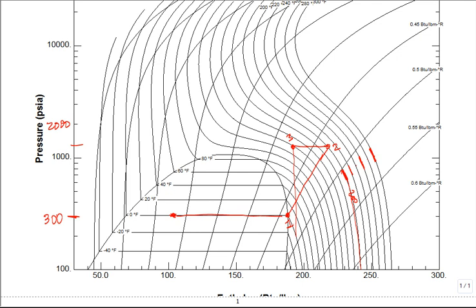You can make CO2 work, but keep going, higher pressure. That compressor is not going to have to just go from 300 to 1200 or 1400. Let's keep boosting it. And that exit temperature out that compressor is going to get really hot. Let's say it goes all the way to 300 degrees F. Do you want to touch that? Do you want to touch that outlet to the compressor? No, you don't. Okay. Now the high pressure is, let's say, above 2000, right?